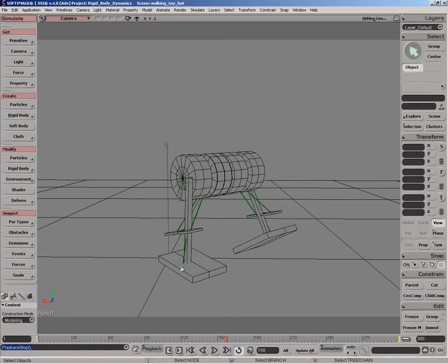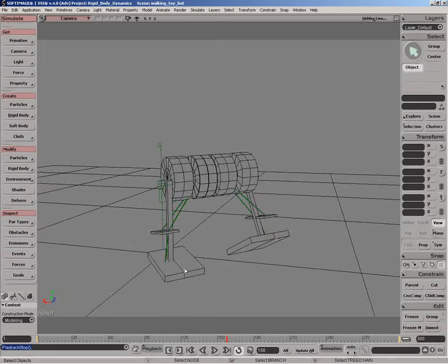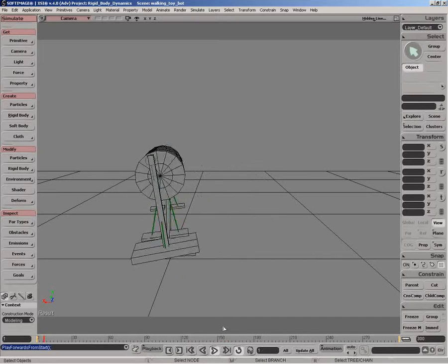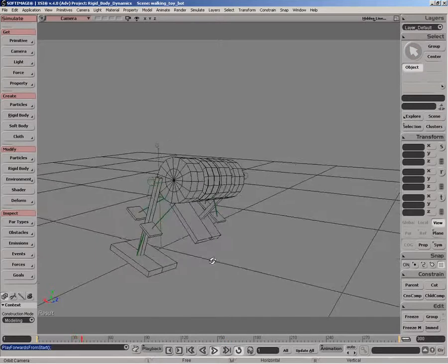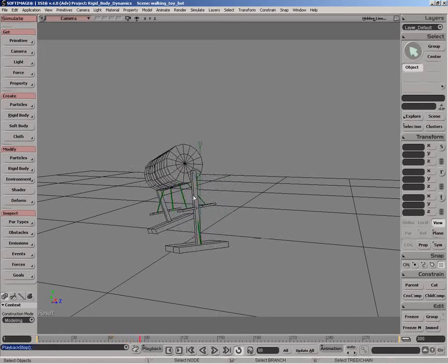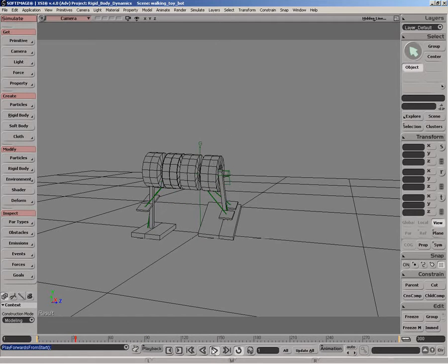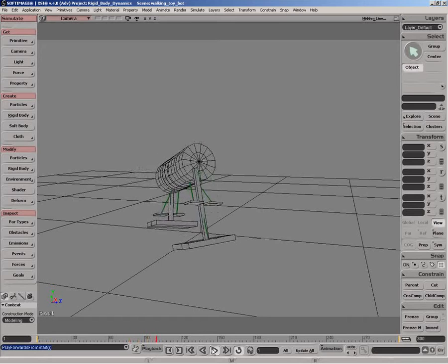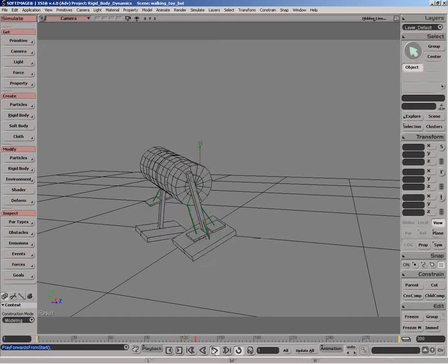And at the bottom, we've got a simple fixed constraint with a foot paddle. And we brought the feet in slightly to keep the thing balanced. And of course, that system is then duplicated and repeated on the other side with the offset in phase of 180 degrees. So we get this cyclical gait pattern. And then we've also got the motor turning the other way, so it'll actually march in one direction.